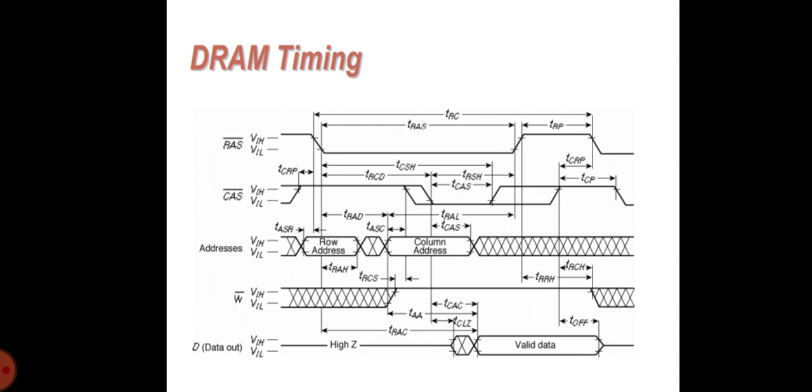For instance, the SE signal cannot be applied too early after the word line decoding is started, since this increases the sensitivity to noise. On the other hand, postponing it for too long slows down the memory, and the separation of these events is a function of the word line delay that might vary with temperature and process variation.